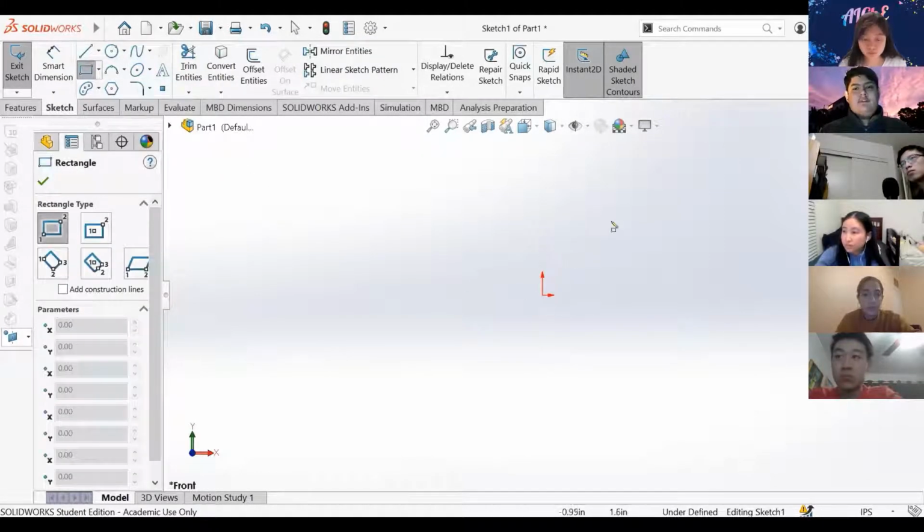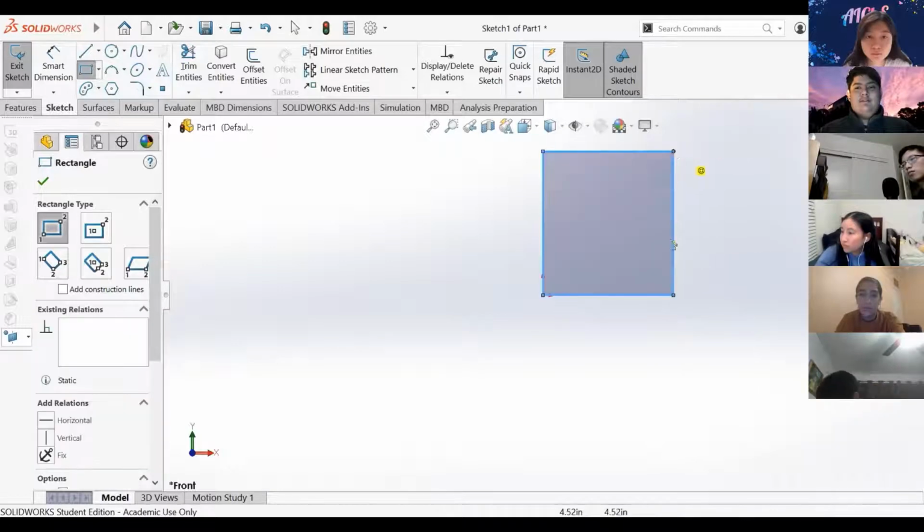If you notice, you can drag your mouse around and it gives you guidance. Here in the center, this is your origin, of course, and then you go up and down the y-axis and then x-axis. What I always do, it's a good practice to start your drawing right on the origin. It makes everything easier in terms of dimensioning. So I'm just going to make a box. And in case y'all are wondering, zooming in and out is with the wheel.